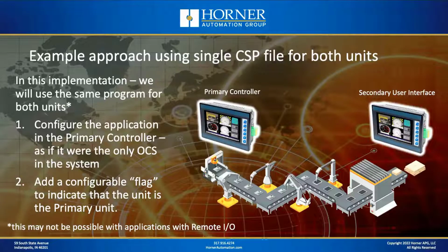And our next example is that in which we're going to accomplish the same thing, except this time we're only going to use one program running in both units. Okay, so we don't have a separate program for the primary controller and the secondary controller. We're going to create a single program that both of them can execute, so that we have one less program to maintain. That's always a benefit if you can do that.